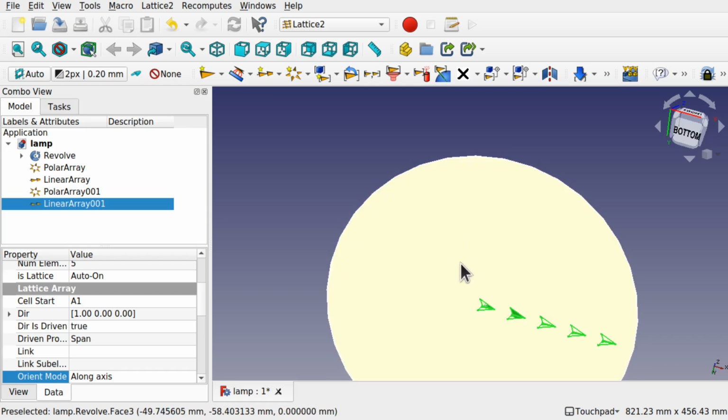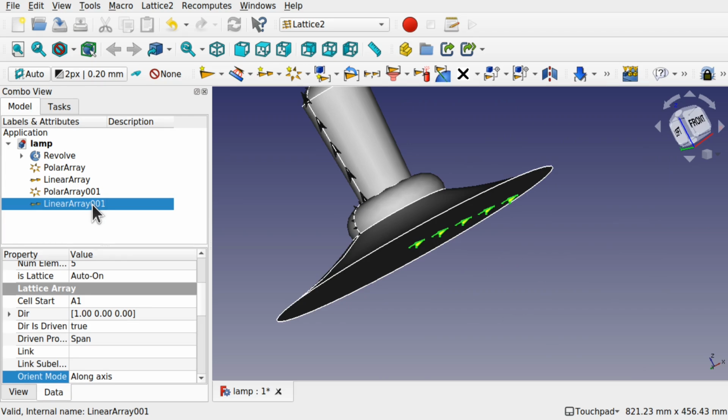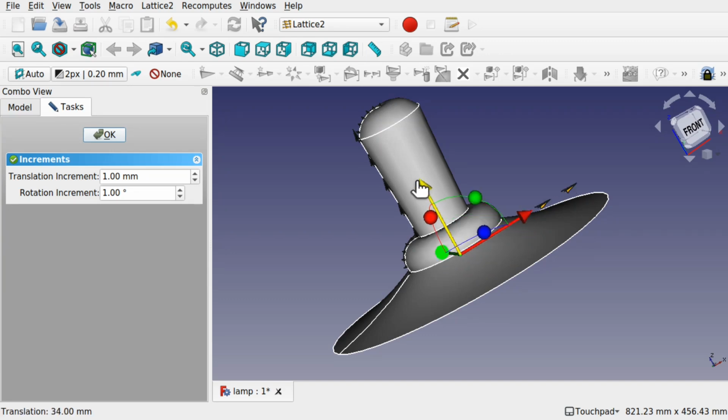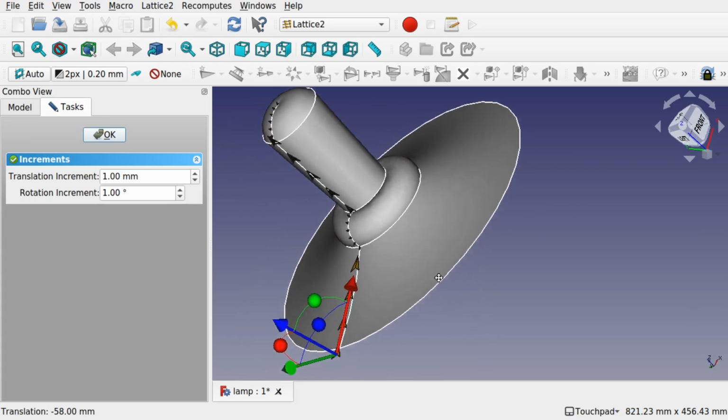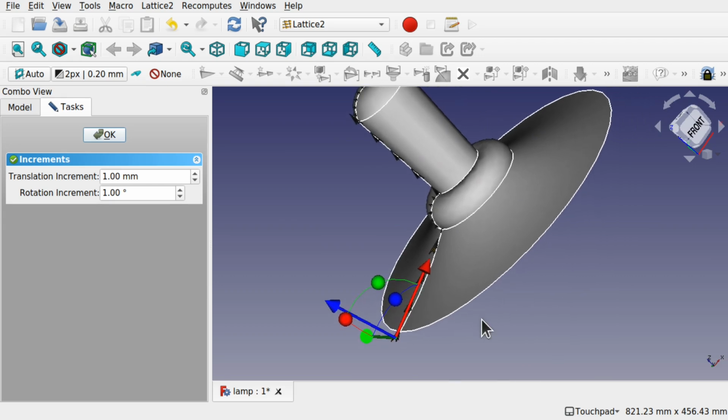This will be placed on the bottom, so we need to transform this into position. So right click, transform, and we can move this into position. And rotate this. If the rotation increment is at say 15, then we just reduce this down to 1. And we can rotate this into position. What we need to do is place it as close to this line as possible. Now there are some problems here. You may encounter a few problems with attachment with this, and we're going to try to recreate those problems so you can actually fix those.